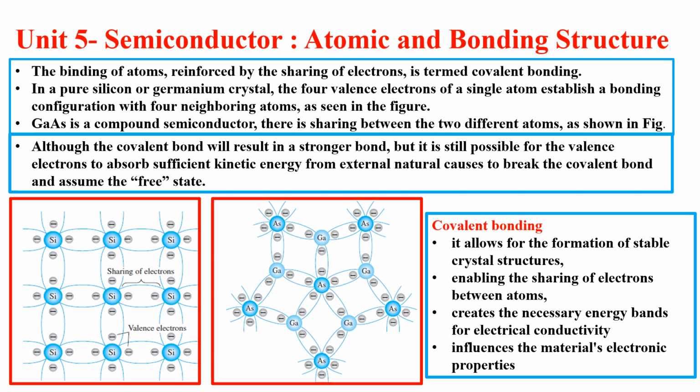At room temperature, there are approximately 1.5 times 10 to the power 10 free carriers in 1 cubic centimeter of intrinsic silicon material. That is approximately 15 billion electrons in a space smaller than a sugar cube, an enormous number. And these many semiconducting properties of silicon inherently depend on the intrinsic free carrier density of the electron.